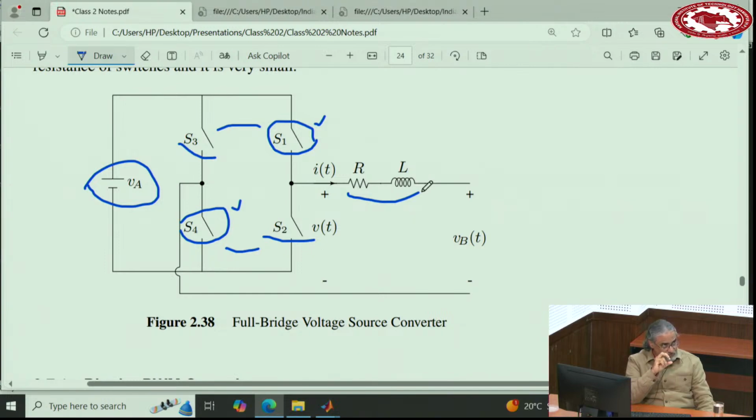So the hysteresis loop of the magnetic material used to make the inductor, we don't want to go into details of that, right? So now that hysteresis loop is smaller. So the hysteresis losses become lower. Immediately one thing: the hysteresis losses of the inductor become lower.